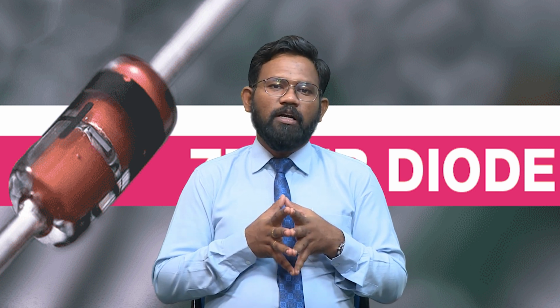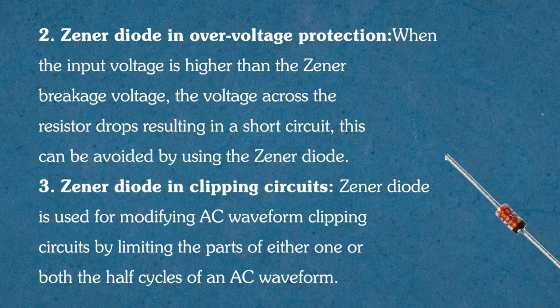Here, the Zener diode is used to limit the current. So, if a current increases to a particular level, and due to this, directly or indirectly, the voltage increases beyond a certain rating, that can be limited using the Zener diode. In this way, the Zener diode finds its application in over voltage protection.